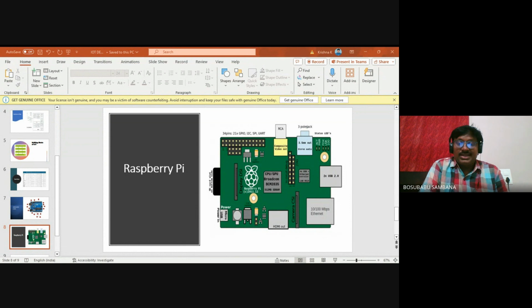The Pi Zero lacks the 40-pin GPIO connector found on all other Pi boards, replaced instead by solderable through holes. The Pi Zero WH fixes this shortcoming. The Pi 4 has a 1.5 GHz processor, while the Pi 3 Model B Plus and 2 have 1.4 GHz and 700 MHz.